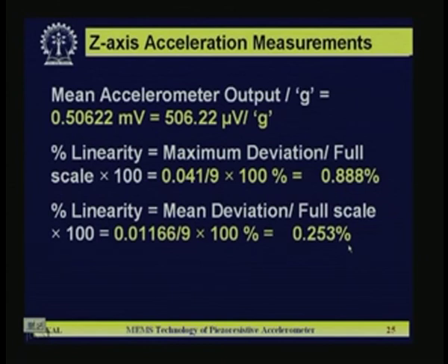And here we are not getting the output as per the design value. The reason is that we designed the flexure thickness as only 20 micron, but later on we measured the flexure thickness to be nearly 30 or 32 micron.